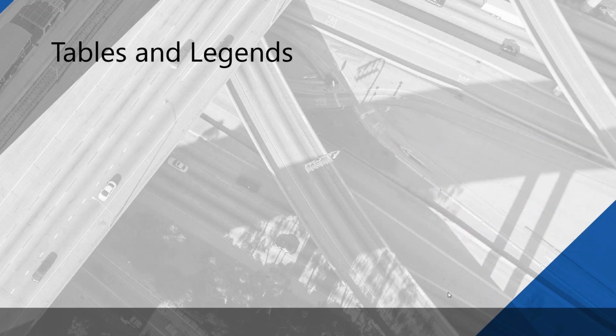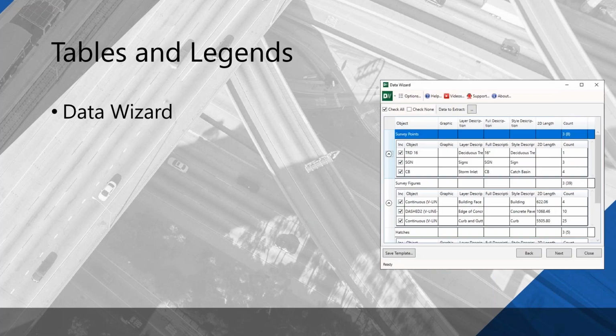Next thing I want to look at are tables or legends, be they in our sheets or on an overall legends sheet in our project. Whatever it is, generating these things can be fairly time-consuming. Again, they're fairly manual. If it's a legend, a lot of people have a one-size-fits-all. They drop it in and then they edit things based on what's in their project. Or they just leave the one-size-fits-all legend or table, and it's showing things that aren't necessarily in the project, not necessarily what we're after. Okay, so Data Wizard is another robust tool we have in the SIM project suite.